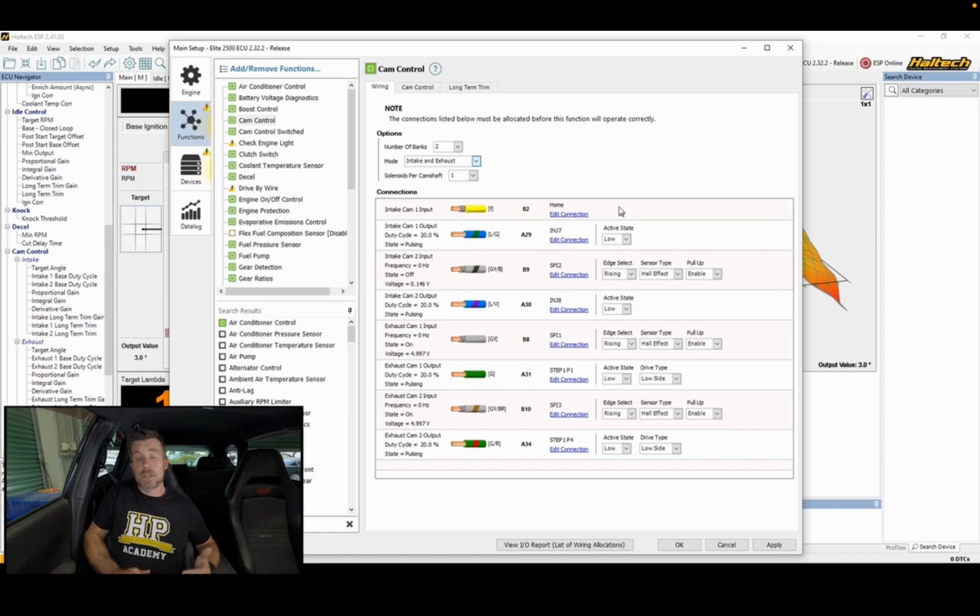So first of all, working down in order, we can see here that our intake cam 1 input, which is our cam position for our intake cam 1, where that's coming from. And we can see that that is the home input, which is what we've just looked at. In other words, our synchronization input. As I mentioned, this does 2 tasks here in the Subaru engine. It gives the ECU information about the engine position, so which particular cylinder is firing at any time, critical for sequential fuel injection and direct fire spark. But in this case, it's doubling its duties here as also giving cam position information.